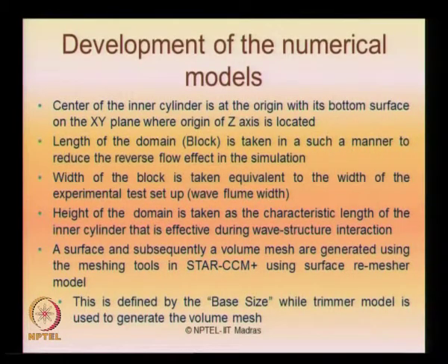Let us quickly see some of the details of the numerical model. The center of the inner cylinder is kept as the origin with its bottom surface on the xy plane. The length of the domain block is taken in such a manner as to reduce the reverse flow effects in the simulation. The width of the block is taken equivalent to the width of the flume. The height of the domain is taken equal to the characteristic length of the inner cylinder that is effective during the wave structure interaction, because the domain has to be defined very clearly in the numerical model.